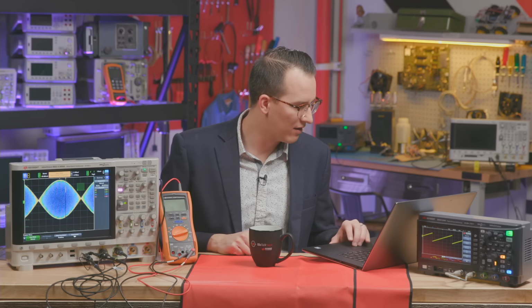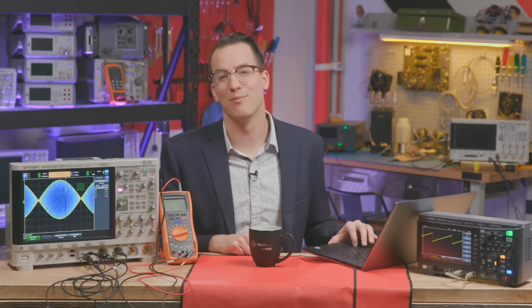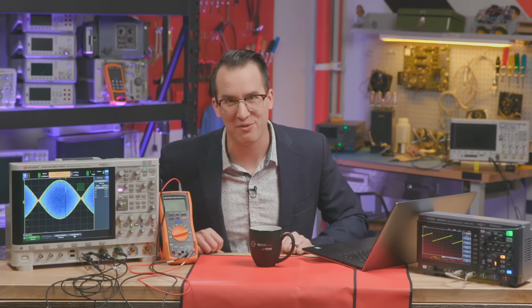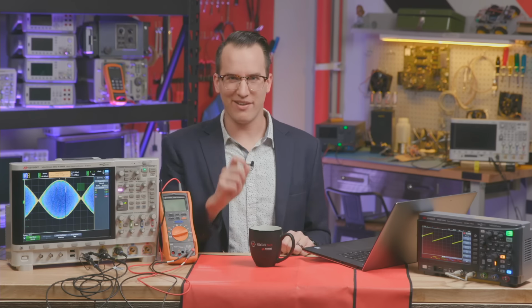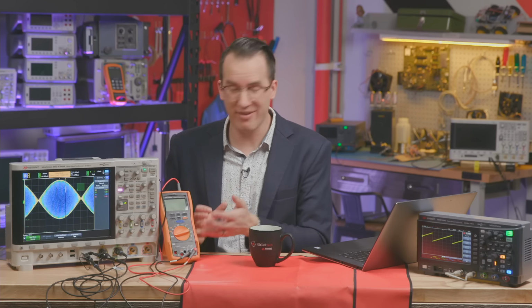Let's see. Benchtop multimeter versus a handheld multimeter. That would be a great standalone video. I'm going to add that to my list of videos that we should create. The nice thing about a handheld DMM is it's super portable. You're not tied to mains, but what you don't get is the resolution that you get on a benchtop DMM. And often the accuracy is not quite there as well. But the same teams are designing the handhelds and the benchtops, so you still get pretty good performance for whatever class of DMM it's in.